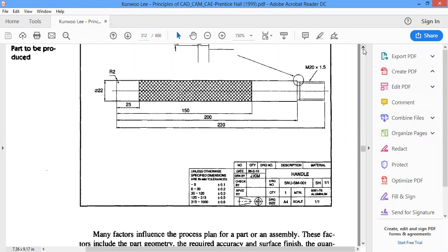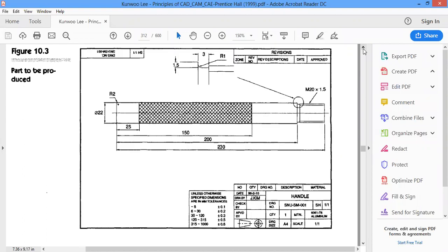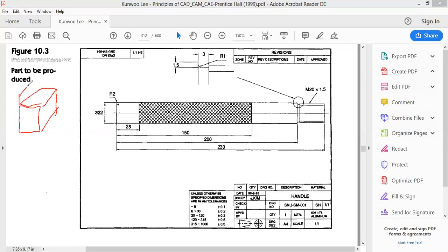And then in the sequence of operations, what will be there is what is the first part that has to be fit, and how should it be fit. So for example, if you are going to have an engine body, and let us assume that for this engine body the piston arrangement and all that assembly is done. Now on this, the engine head is going to be placed onto this engine body, right?